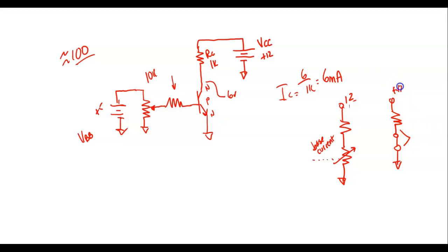So how much voltage will the transistor drop now if it's a closed switch? Even if this is 12 volts, that guy right there is going to drop all the voltage, right? So the transistor would drop 0 volts. And if I come over and open up the switch, and that's 12 volts, how many volts would the transistor drop?